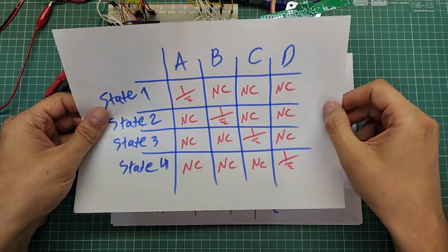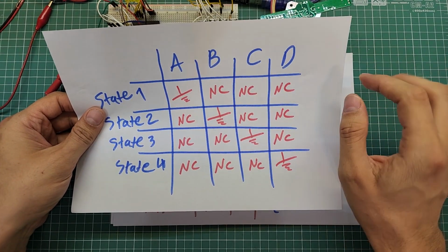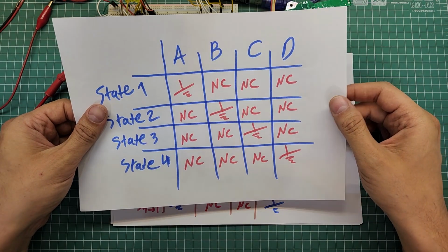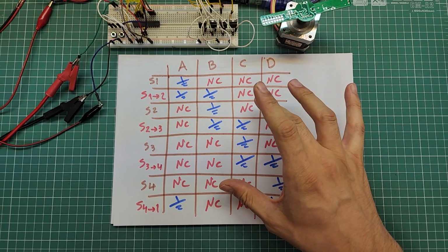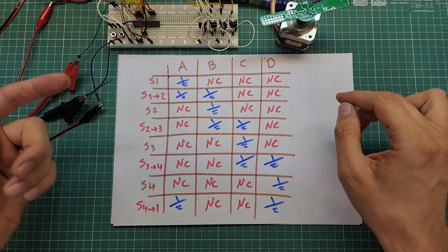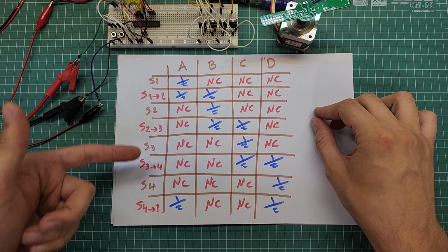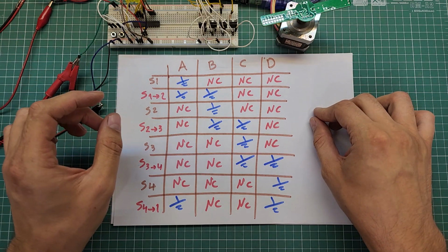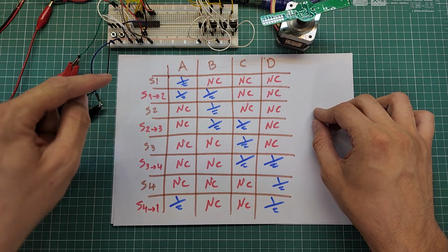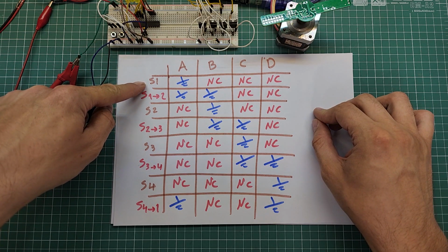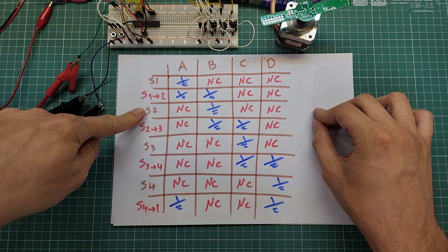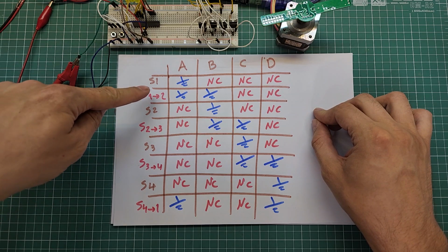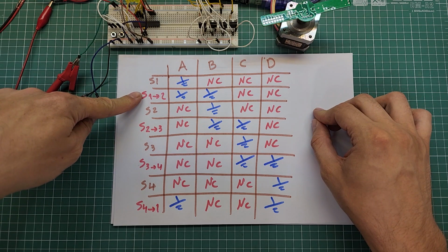Dividing a single step into two sub-steps is super easy. If you are driving the motor using a unipolar method like what we are doing in this video, you only need to expand this table into this one. It is very clear. These states between main states, I mean this one, this one, this one, and this one, are combinations of the main states. You see, in this state, winding A is on and winding B is off. And in this state, winding B is on and winding A is off. But in this intermediate state, actually these two are on at the same time and create a half state.